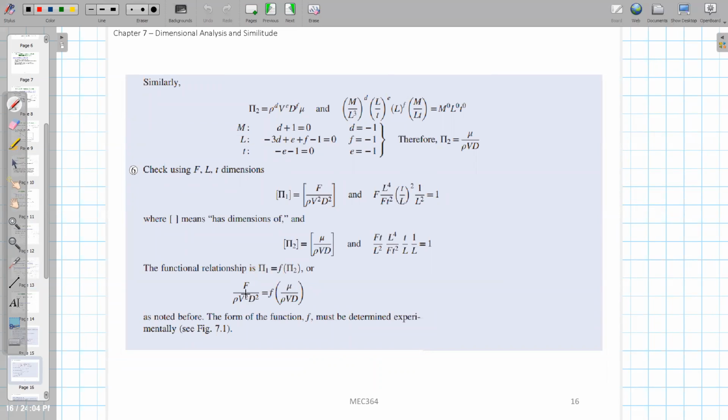After you do the dimensional analysis, even if I do not know any governing equation, I will know that if I want to do experimental analysis to study the drag for a sphere inside a uniform flow, I only need to measure the Reynolds number, because this is a reciprocal Reynolds number.